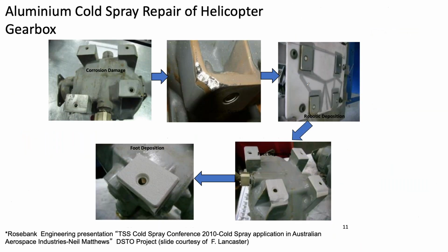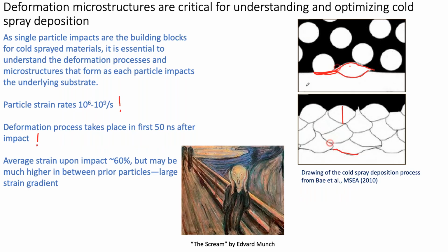sorry, trying to go back to where I was talking about that. By the way, this is a crude estimate, although I keep seeing these numbers pop up throughout the cold spray literature, so I don't think I'm that far away. There are people that do detailed mechanics simulations of this process, and they arrive at this range of numbers as well. There are those that predict, and maybe even some limited observations of evidence that shows, potential localized melting, particularly those that ascribe to an adiabatic shear instability model, where you get very localized heating. But in all the work that I've done,